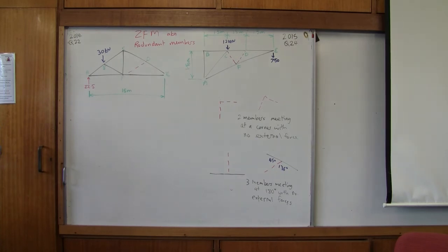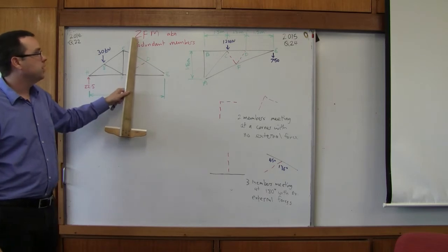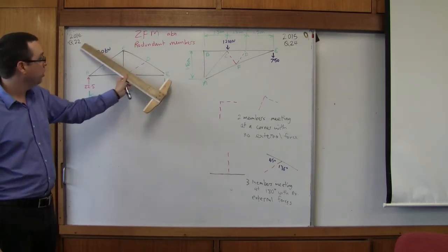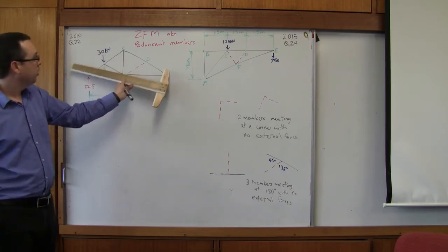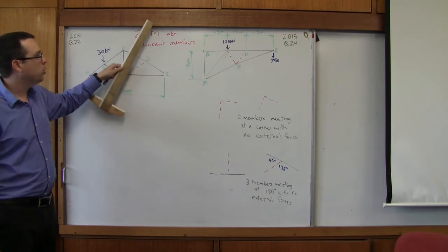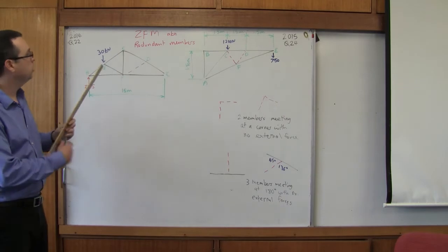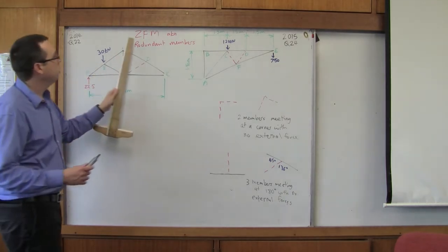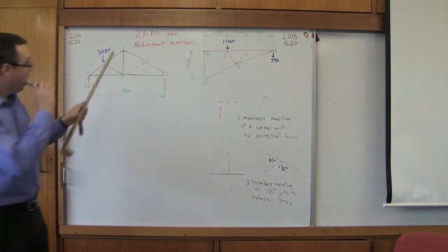First step with trusses, we're using method of sections. We need a section line to cut through. It has to be something that cuts through DF and can't cut through more than 2 other members. So we could go this way. That's cutting through 4 different members though. That's too hard, right? And we can cut that way, yeah, but generally we're going to... I'm not saying it should always be vertical cuts, but often it will be a vertical cut or vertical-ish. Anyway, so what we're going to do is we're going to put our cut here.